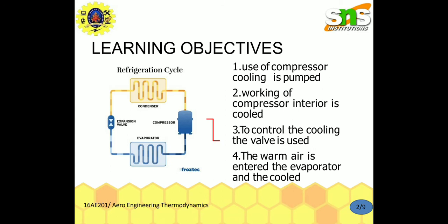The operating principle of the refrigeration cycle was described mathematically by Sadi Carnot as a heat engine. A heat pump can be thought of as a heat engine which is operating in reverse. Refrigeration cycles can be classified as vapor compression, vapor absorption, gas cycle and Stirling cycle types. The vapor compression cycle is used in most household refrigerators as well as in many large commercial and industrial refrigeration systems. The thermodynamics of the cycle can be analyzed on a diagram as a reference.